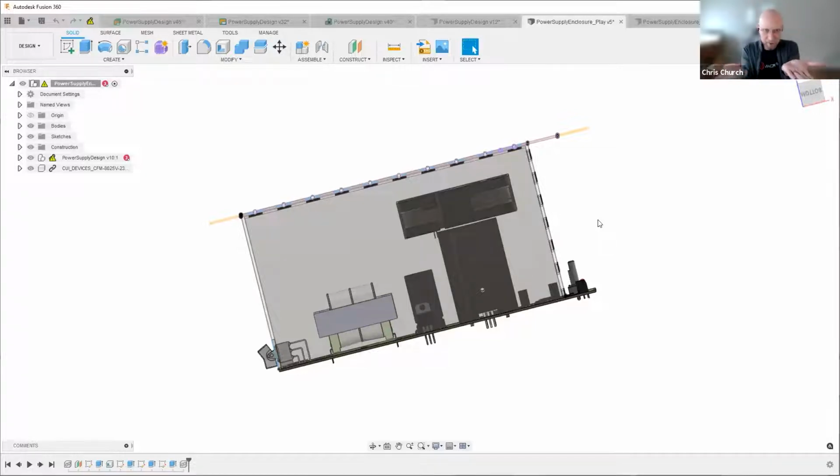The perfect world is someone can take this as a clamshell, connect it in, and then pop that PCB on top there like that, and then we're ready to go. So the cable's long enough to do that. It may be too long, and we'll talk about other strategies with you about, for example, we might zip tie that cable together to keep it from flopping around in there and keep it from getting pinched. If we have real heat issues, our team would talk about how we add some attachment points to the enclosure itself to route that cable in a certain position. But those are the kind of things that we can do when we're sitting here working with the 3D model.